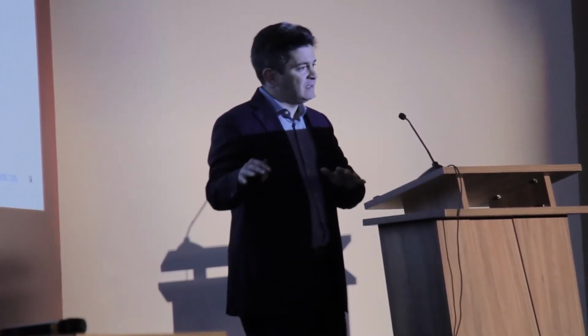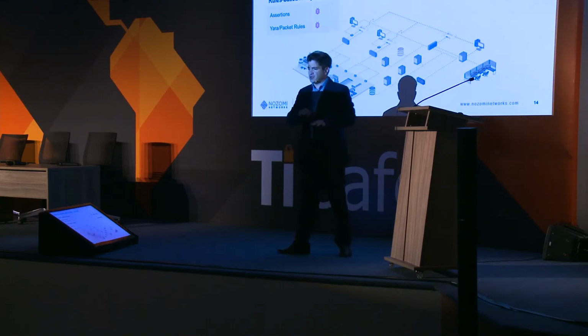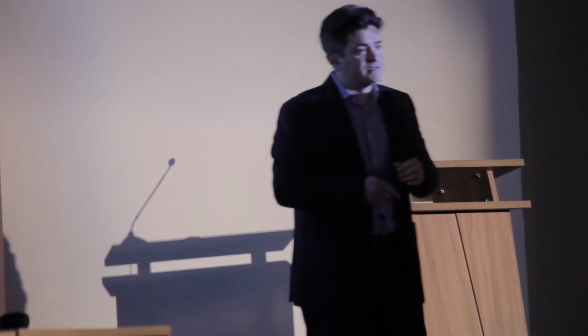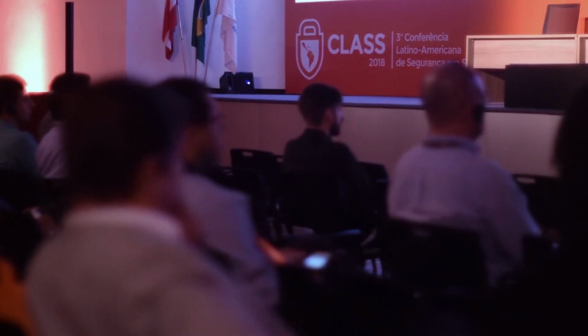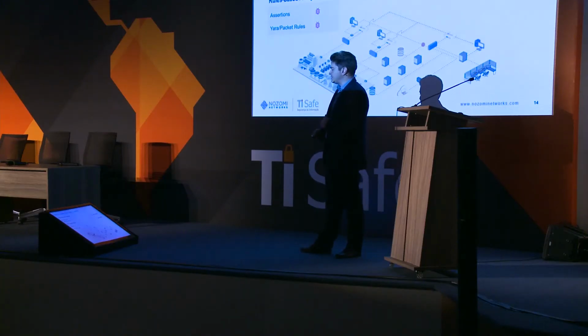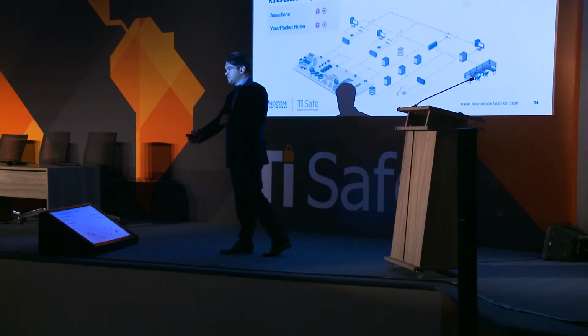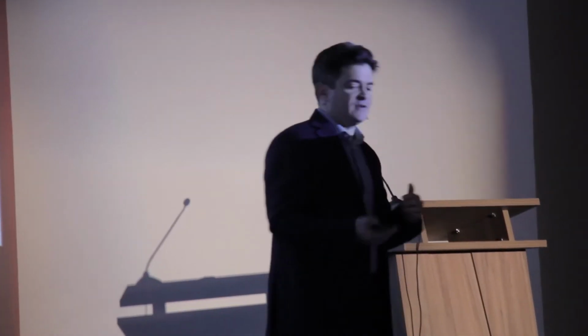The second step usually has to do with lateral movement, once you're infected. Just like the malware is trying to discover assets and try to know what to infect next, you have to be able to catch that lateral movement and detect it. And again, you need both signature-based and anomaly-based detection. And last, in a traditional attack, you have the actual harm, where you actually change a pump speed or change a rotation of a turbine. And that also is detected with behavioral-based and anomaly-based detection.